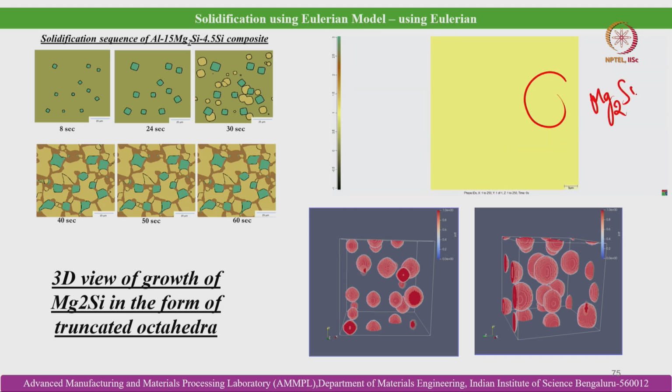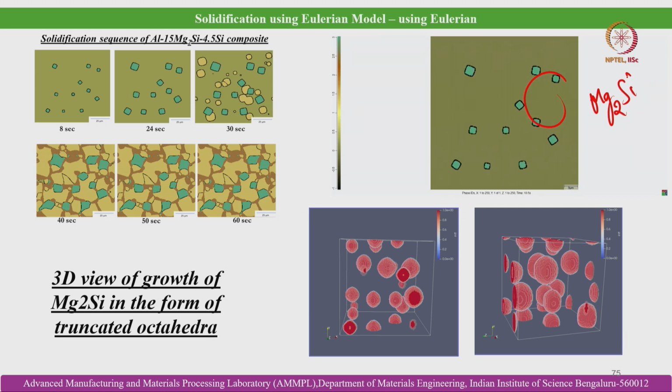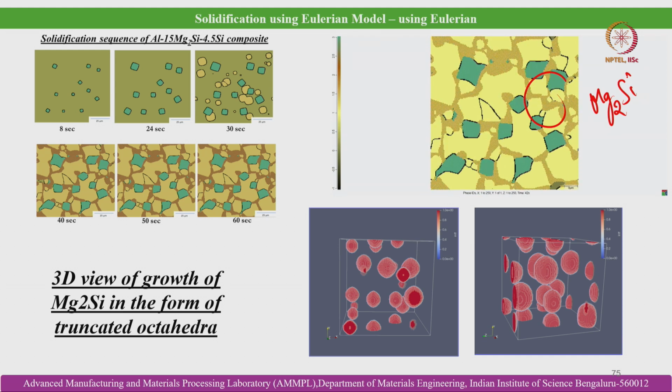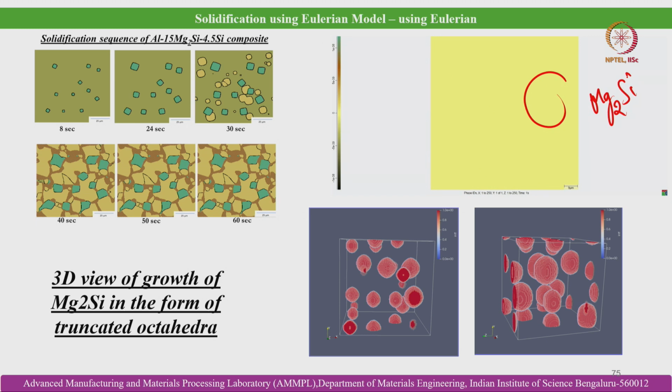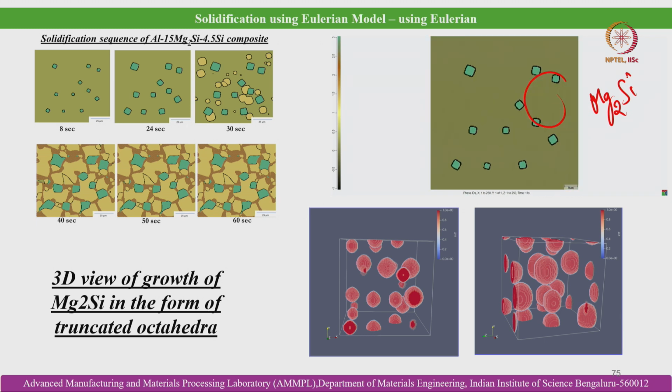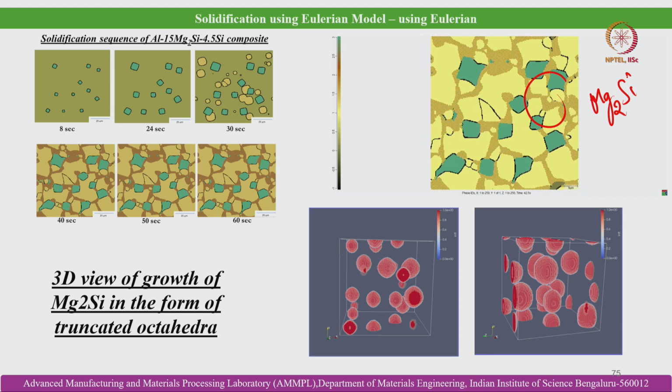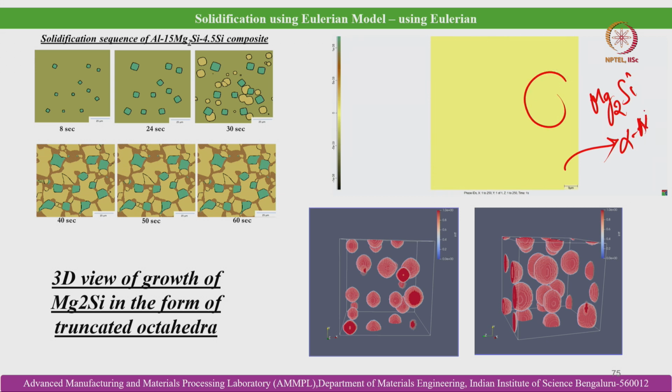These are the ceramic reinforcement that are generated in situ within the melt during solidification, that is, the reaction of the pure magnesium and the extra silicon present within the composite matrix is responsible for the generation of Mg2Si particulates, and once the Mg2Si is formed, it serves as a heterogeneous nucleating agent for alpha aluminum. This white phase is nothing but the alpha aluminum.